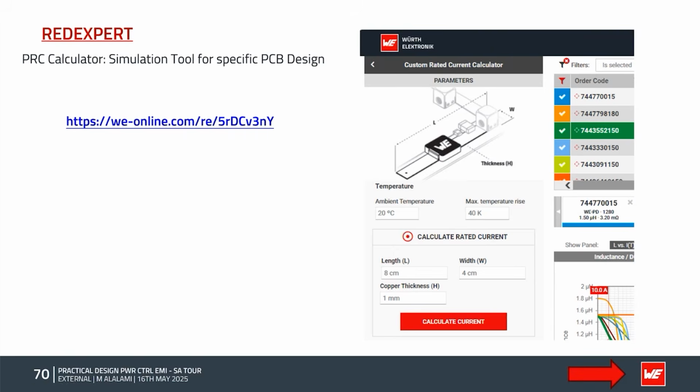Here you can utilize this tool, and I've shown you just a snapshot of it. You can put in your own length of track, your own width of track, your own thickness of copper, 35 micron, 1 ounce copper, 2 ounce copper, whatever you want to use. And accordingly, it will re-rate your inductor based on the size of your tracks and based again on a 40 degrees maximum temperature rise.